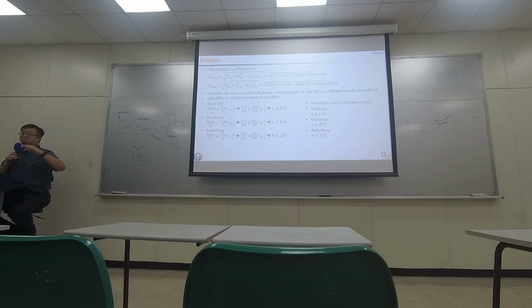So averagely it's not very large, but the amplitude changes dramatically, plus and minus, plus and minus. So somewhere inside the shaft is being compressed and tensile, compressed, tensile dramatically. So if you apply this in your fatigue model, you realize all the safety factors reduced.